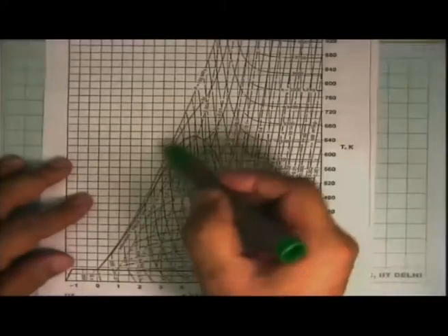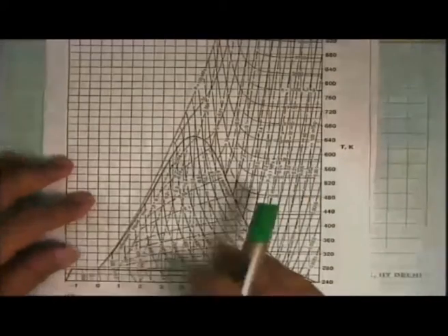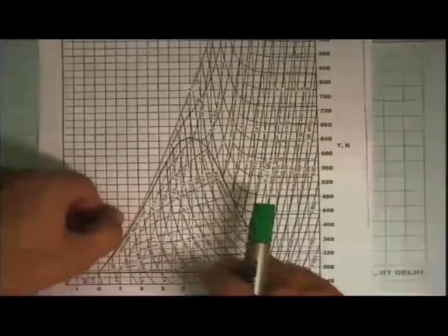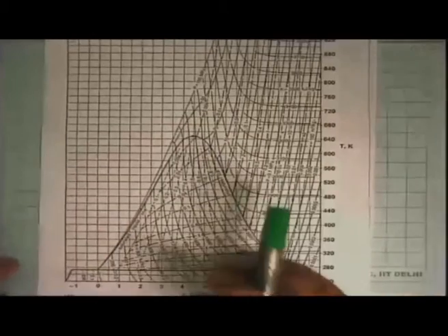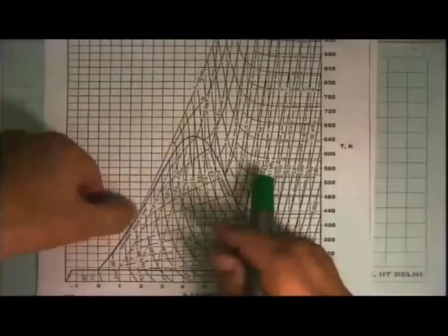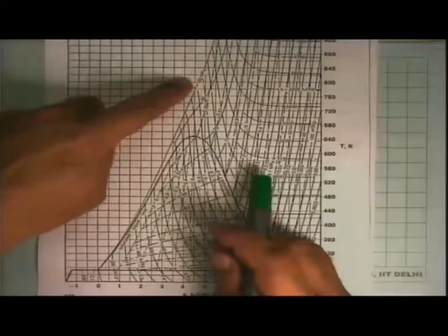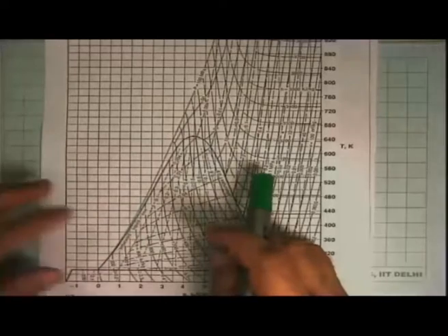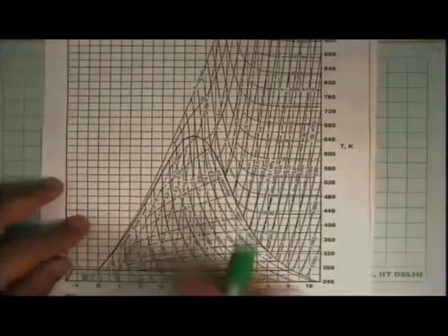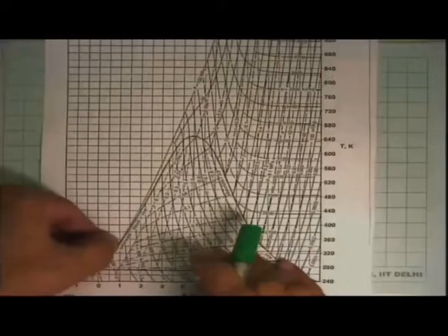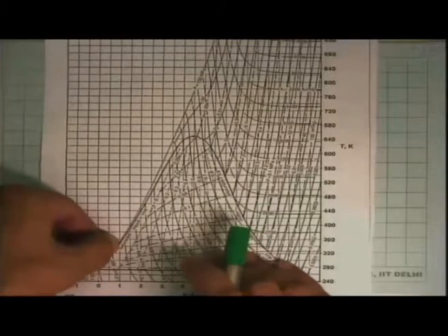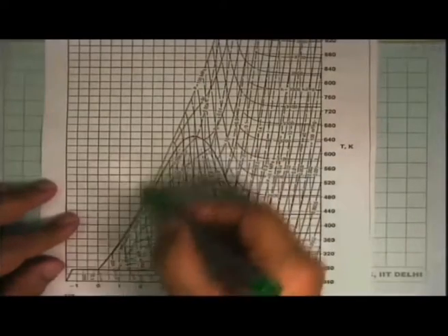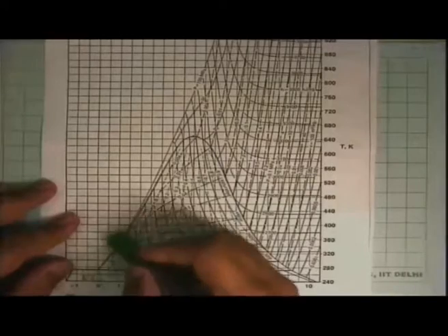And then if you see this part, practically they have not drawn anything over here. And we know that all these states on this side, and this is now this extreme line on the left, is 100 megapascal, very, very high pressure. And this is the saturated liquid line. So pumping water from 1 bar to 10 bar won't even show up on this line. It will be a very, very small line somewhere squeezed in between here. And that's because the dependence of entropy on pressure is very, very weak. And so we cannot see those lines here.